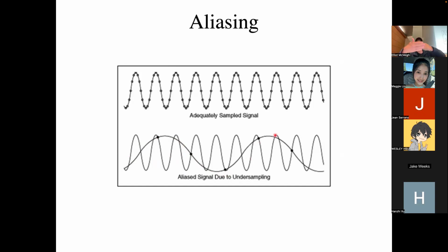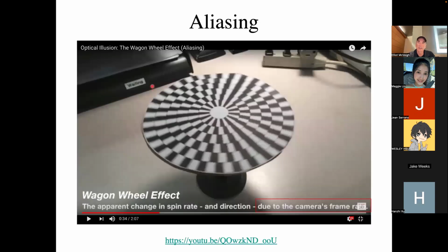And so those two methods are superimposed on each other. I don't know which one's which when I do this sampling. Is it the high frequency one or is it the low frequency one, right? That's called aliasing. That's confusing signals that are actually high frequency signals with lower frequency signals in your field of view. This is a really good example. You've all seen this.